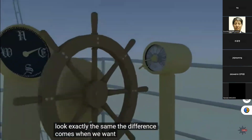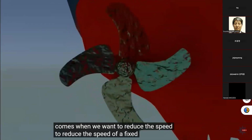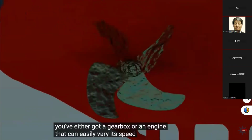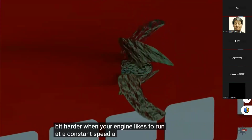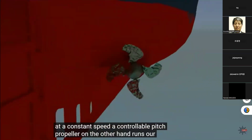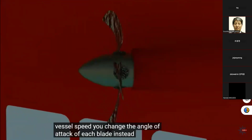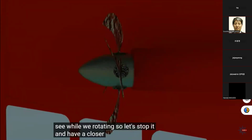The difference comes when we want to reduce the speed. To reduce the speed of a fixed propeller, you have to slow the rotation. Very easy if you've either got a gearbox or an engine that can easily vary its speed. It's a bit harder when your engine likes to run at a constant speed. A controllable pitch propeller, on the other hand, runs at a constant rotational speed. To reduce the vessel's speed, you change the angle of attack of each blade instead. It's hard to see while rotating, so let's stop it and have a closer look.